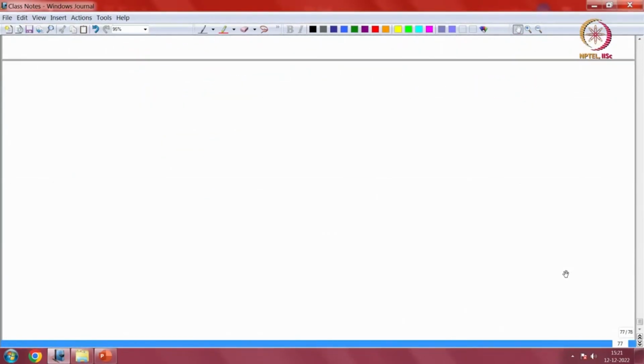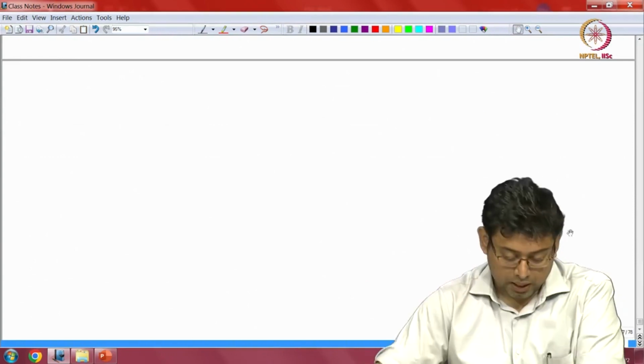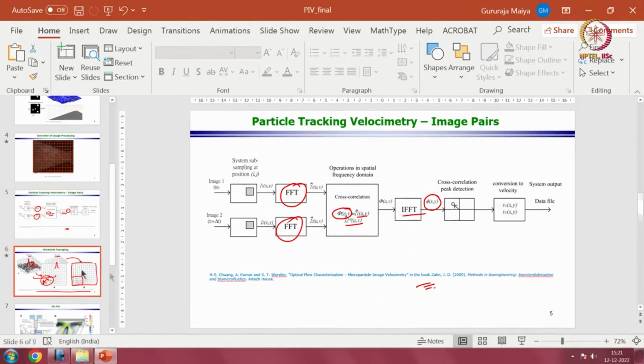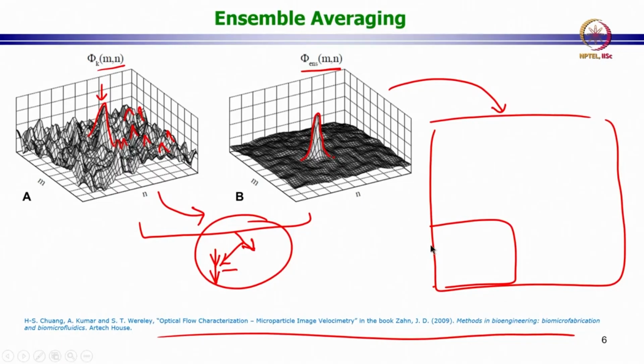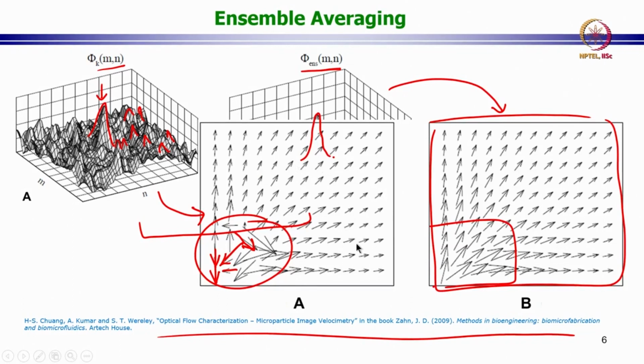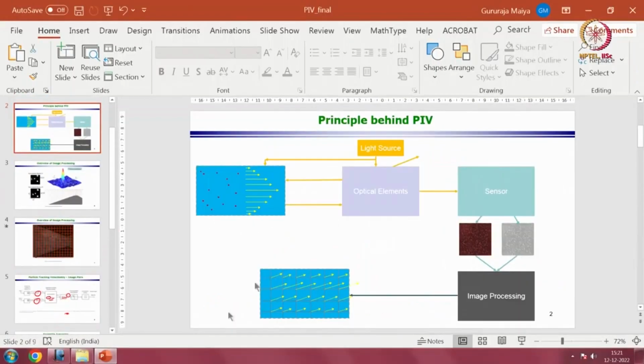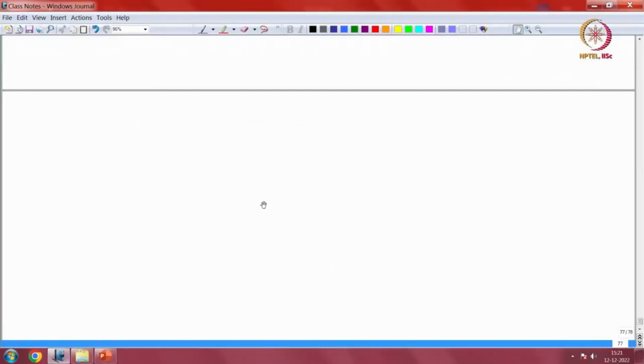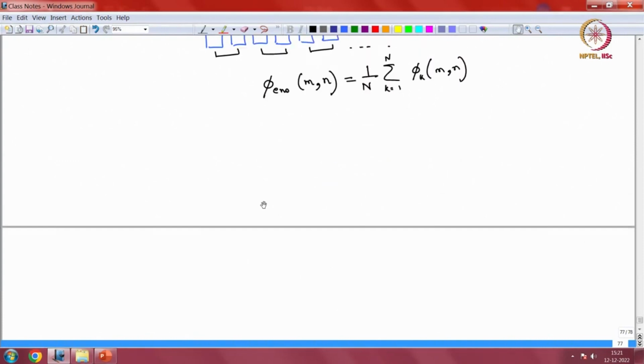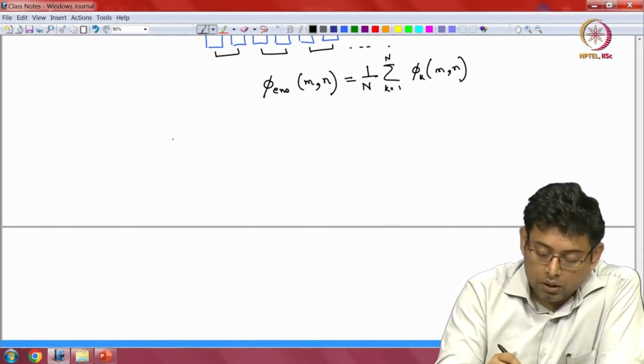Okay. Now, as you have seen, I'll just quickly go back to this image here. These velocity fields are two-dimensional, right? So all these images that we have been discussing, these two images that are being used, are representative of two-dimensional systems. So conventional PIV is two-dimensional in nature, which means that if you have a significant out-of-plane motion, that does create a problem.